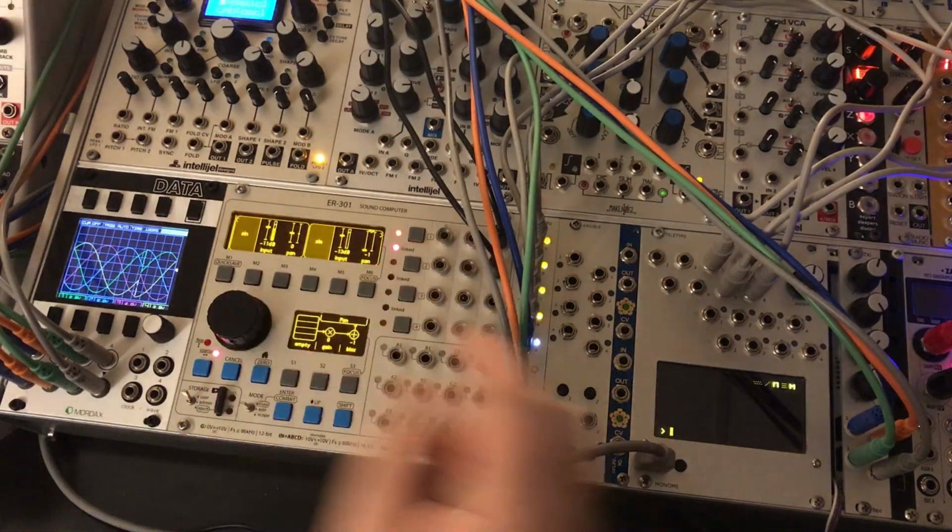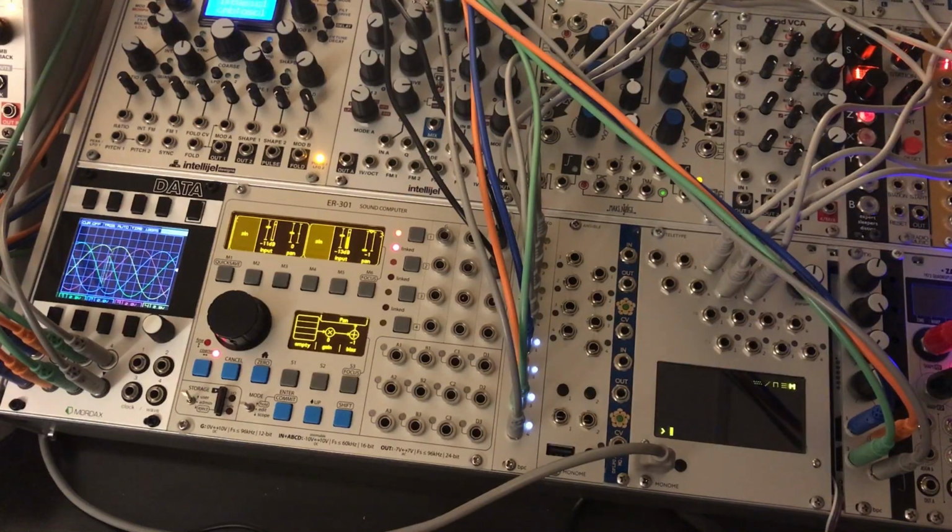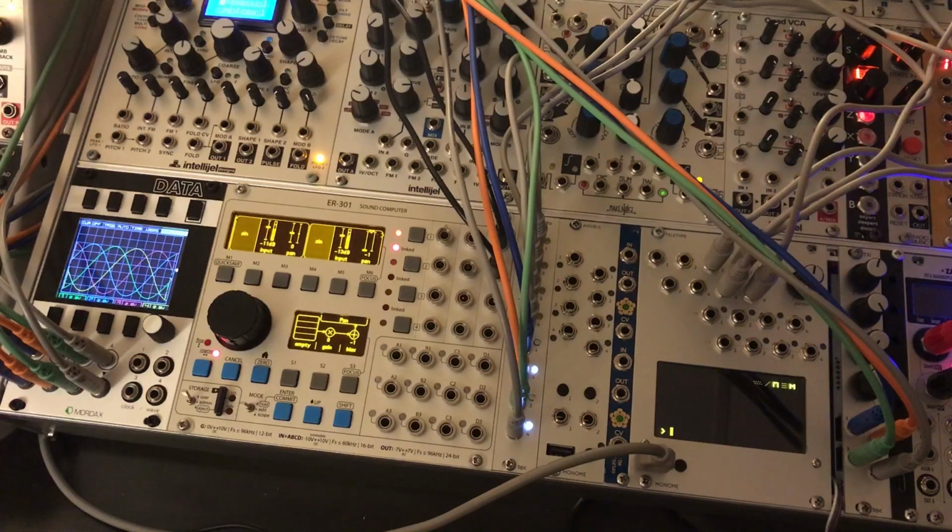Up here on the TR outputs of the TXO, we've got these generating trigger or gate signals. Essentially, the output expander has 4 independent metronomes, so they can all run at independent rates. Here we've got them synced up, but we can use those in a variety of different ways. In this case, we're using it to trigger the envelopes of these different notes that are being generated.